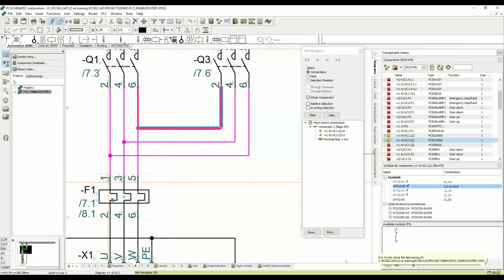The reason for that is that when the program interprets those dots, it will simply look at the dots and say where the dots are the shortest. That's where the wires are double or parallel, so two connections down here. And this line up here and that line down here have exactly the same length. So the direction from which it reads the diagram means something, because this is simply the first one that it will read, and then, okay, we'll just take that one. That's the shortest one then. But it might just as well have been that one here, meaning that you don't really know how things are connected here. We know that's not really a problem, but we do know about that.